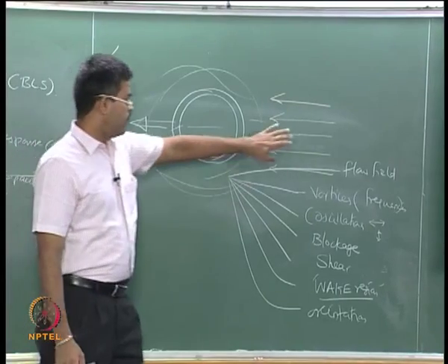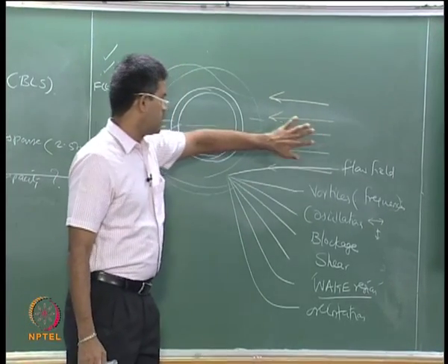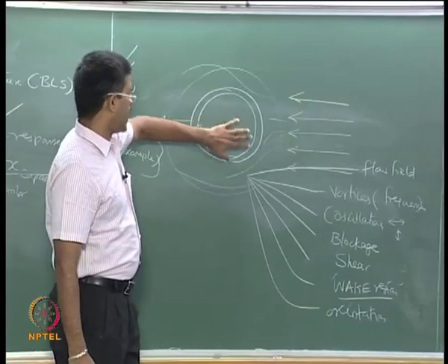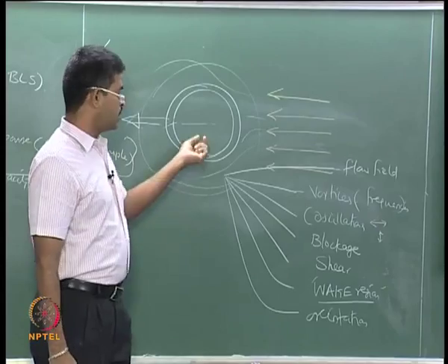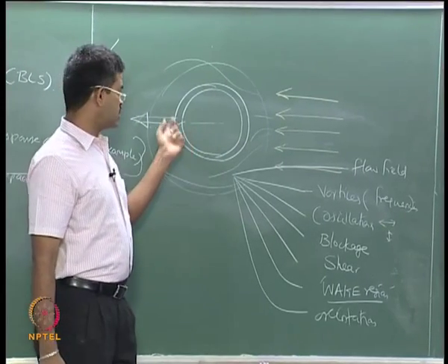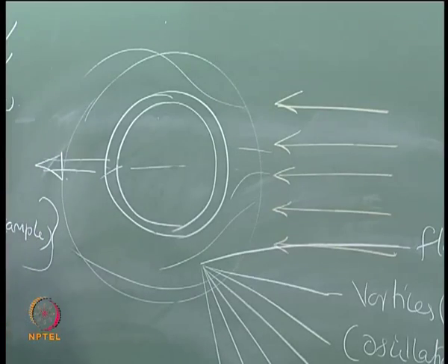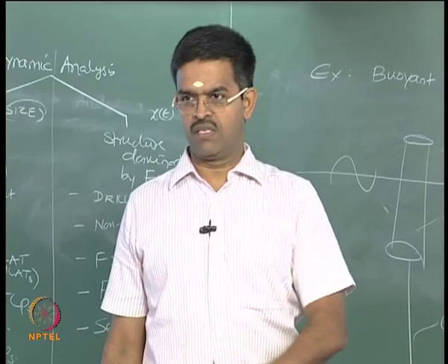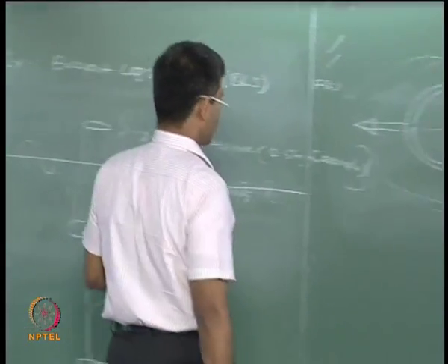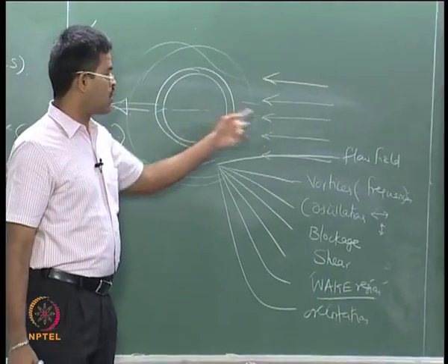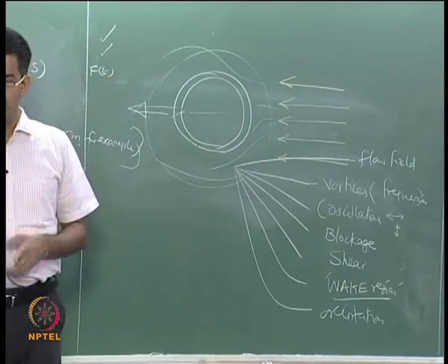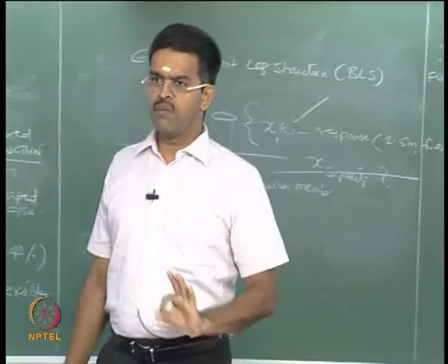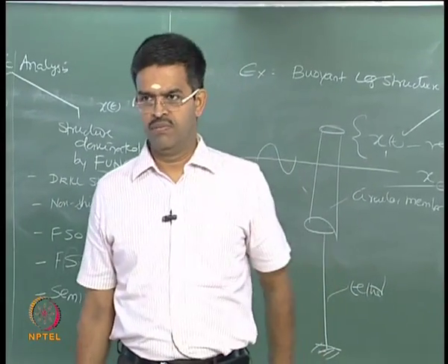Why? When the fluid attacks or, let us say, acts on a given structural member, the fluid field around the member tries to disturb the position of the member. So the restraint forces on the member are developed only to counteract this, okay, that is what we say indirectly as fluid structure interaction. On the other hand, the structure is not exerting any force back on the fluid regime, it is only developing restraint forces which are essentially responsible to keep the member in geometric location and position.